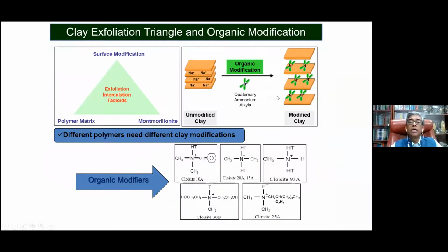So how does this nano clay work? There is what we call an organic modifier. In all of the nano clay, in between those platelets, there is a green modifier. You can see that they are there. These modifiers make the nano clay better for dispersion or for making master batches. If we take unmodified clay, we will not be able to mix. If we take a modified nano clay, then which kind of organic modifier is very important, and the modifier stability is also very important.